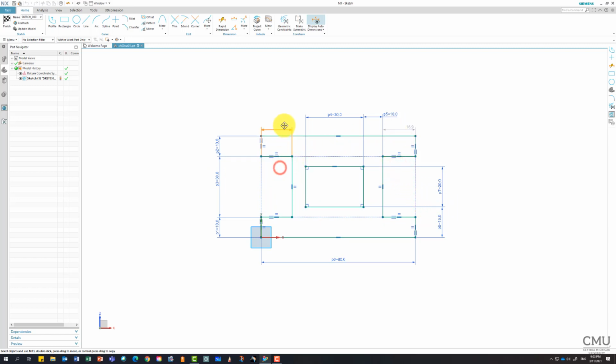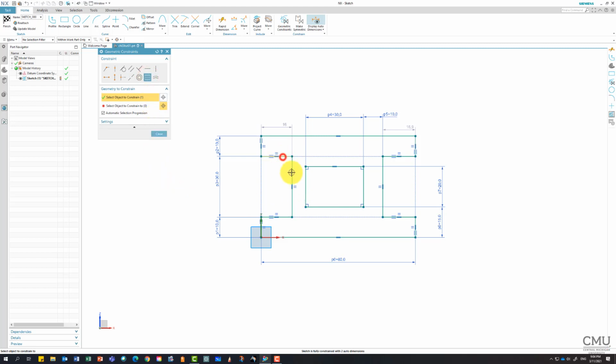So as you can see, oh, that's why we didn't put the equal dimension between these two yet. But think about it. I already have dimensions for this. If I'm putting these two together, I'm pretty sure it's going to work out. So let's see how it goes. So I'm going to add a constraint, equal length between these two. There you go. Did you see that? Right away, one of these is gone.